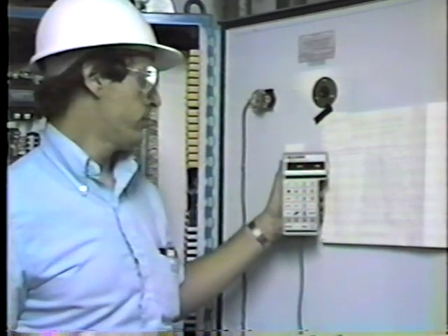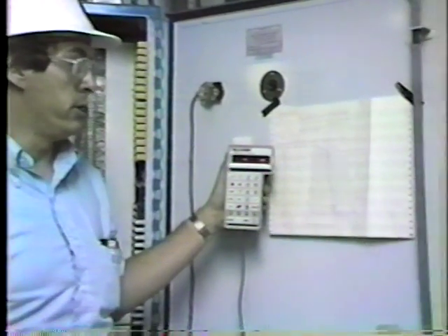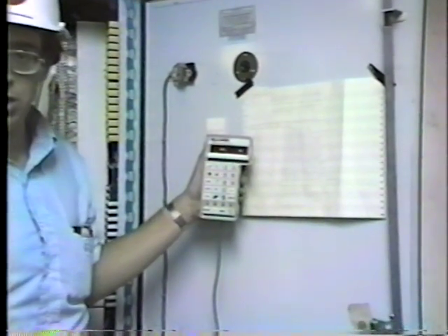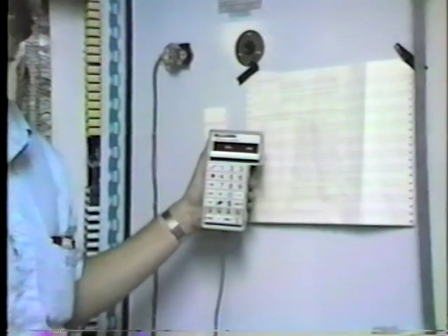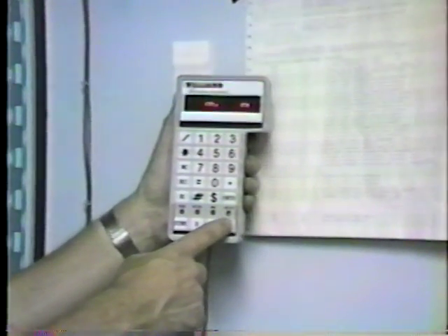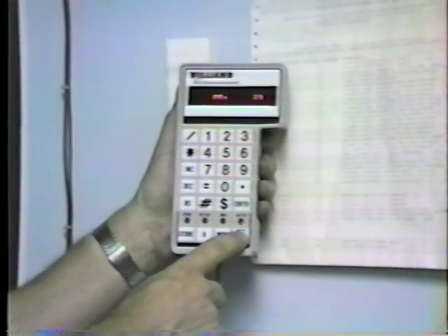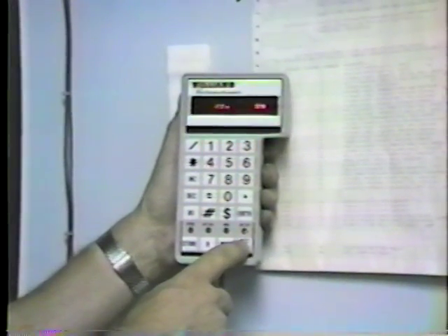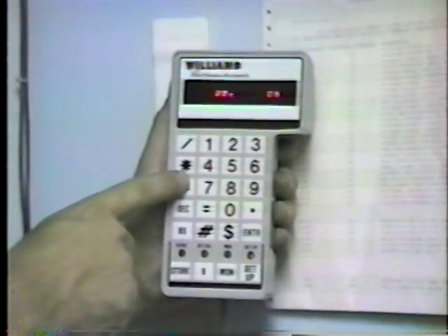Number 20 is the mill speed minimum alarm value. Exactly like the spinner, except it's looking at the pulverizer motor tachometer. It's also currently set to 0, but we'll probably leave it with a setting of 5 or 10%. Why don't you do that at this time so that we can look at it?